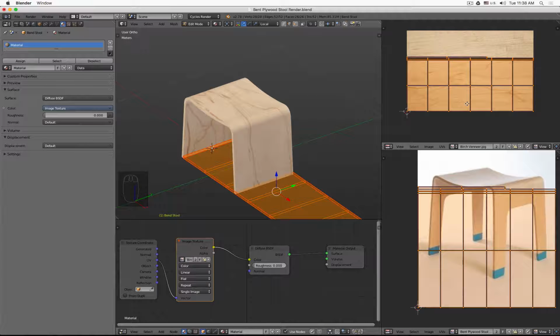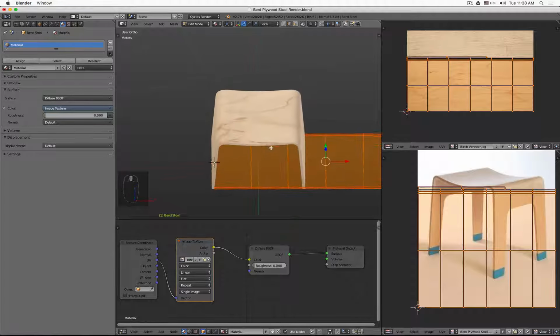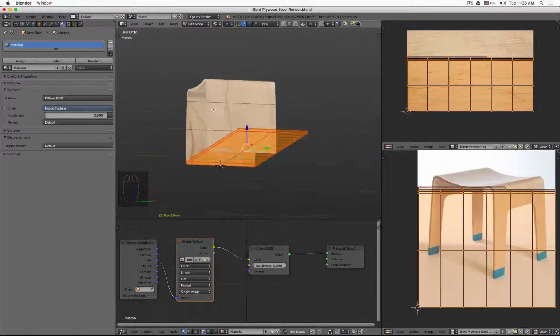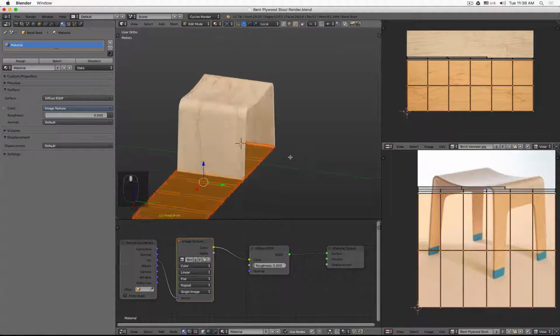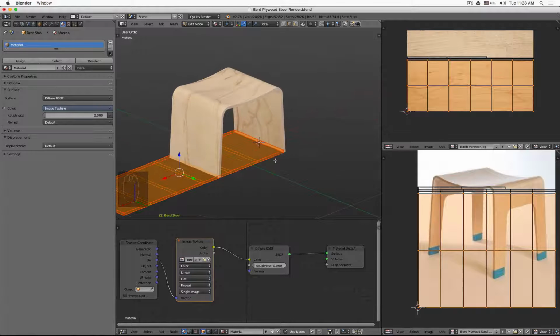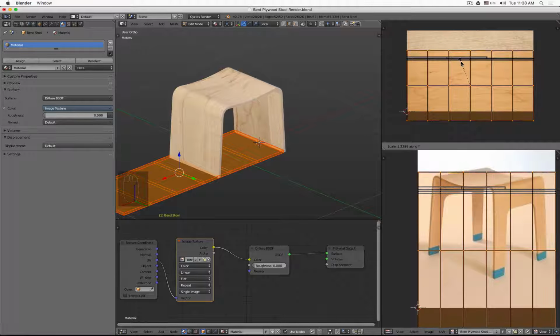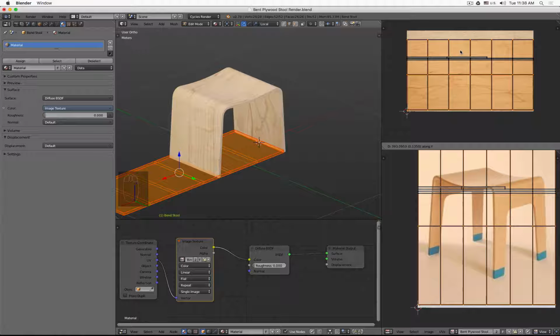Okay, so but it seems that this texture size-wise is close. Maybe I want to add a little bit more of my texture into it. So what I will do is press L onto this one and this one, Shift L, and then L. So now I selected in the UV editor the top and the bottom face. S and Y, I can scale them apart a little bit. G and Y, and move them up.